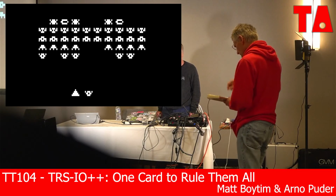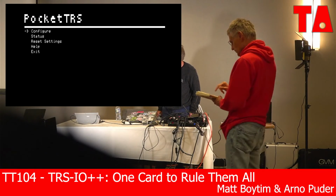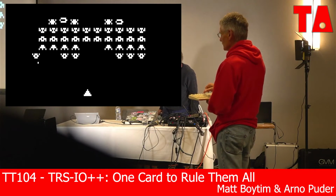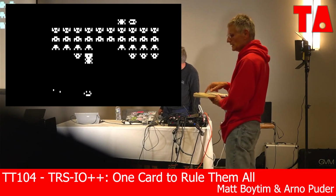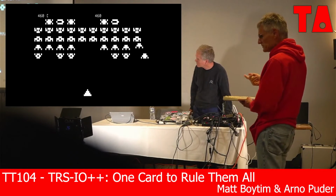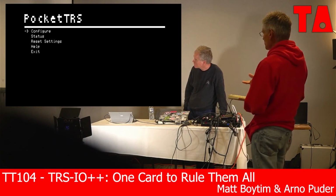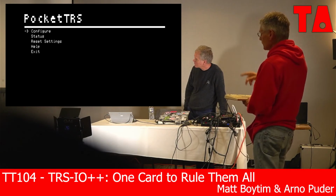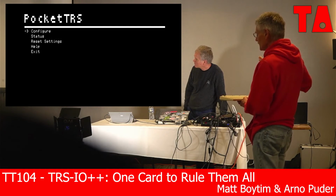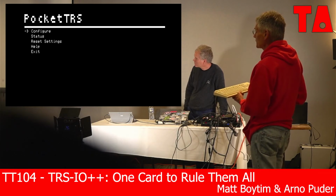So Arno wants to demonstrate the setup screen. As he said, whenever you hit the F5 key, the ESP32 actually issues a bus request to the Z80, which then stops the Z80. It issues a bus acknowledge back to the ESP32 so that it knows it has the bus, and then it's able to access the video memory directly. Then he copies out the memory, scrolls his screen in, and when he's done, he scrolls the TRS-80 screen back.